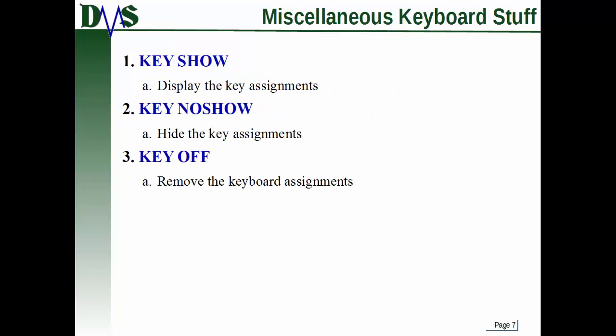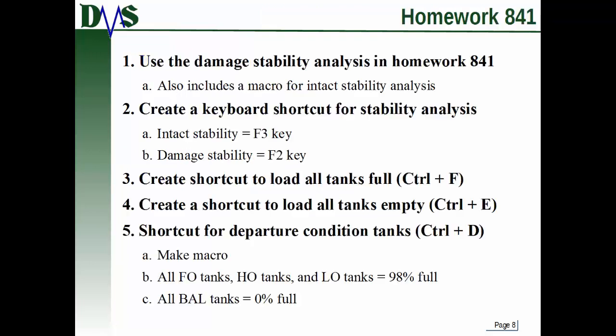Okay, a few more miscellaneous key commands that I have to show you. First off, key show displays those key assignments. They may not be there otherwise. Key no show will hide the keyboard assignments. They still work, they're just not being displayed. And then finally, key off deletes any keyboard assignments that are already there. It removes the keyboard assignments.